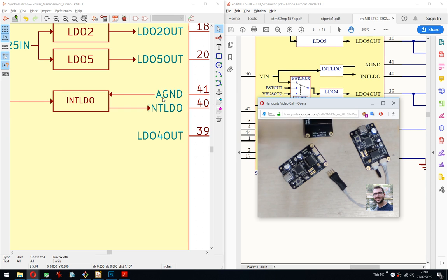You've got the plus line, the ground, and CAN H and CAN L. I will use that to apply power to the isolated side, and use my oscilloscope probes to probe the CAN L and CAN H lines.